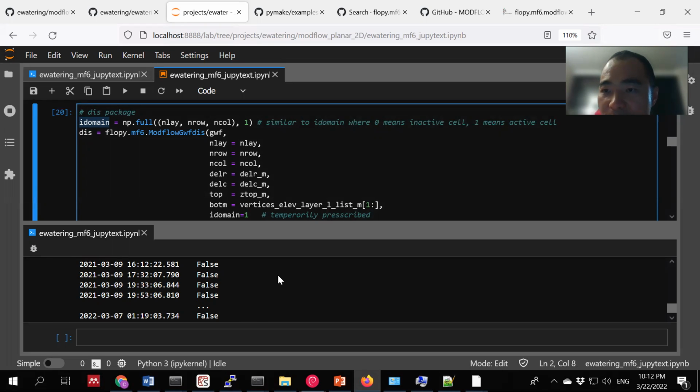This is very important when at one location you have 3 different types of soil, whereas at another location the vertical stratigraphy only has 2 types. That really means that the middle layer is not a cell at all, so you can use -1 to get rid of that. But for this application, that's not important. Everything is 1.